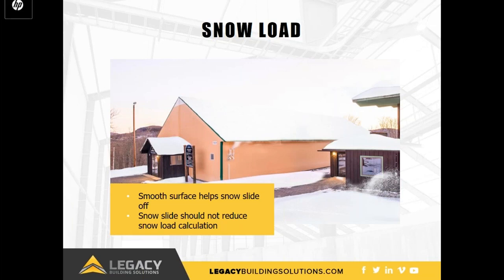In many parts of the world, snow places significant pressure on the building roof. Any reputable building manufacturer will calculate the roof snow load. The building's ability to withstand snow depends on the shape and angle of the roof, the building's exposure, thermal factors, obstructions on the roof such as vents, and of course the roof cladding. Fabric has a smooth surface which makes the snow slide off it more quickly. In snow locations, Legacy buildings have at least a 2 to 12 roof slope which helps the snow slide off. Some fabric building manufacturers incorporate reductions in roof snow load based on the snow slide characteristics of snow on fabric. However, applying the full snow load requirement as stated in the building code ensures that the building is fully compliant and it provides a high level of safety to the building design.